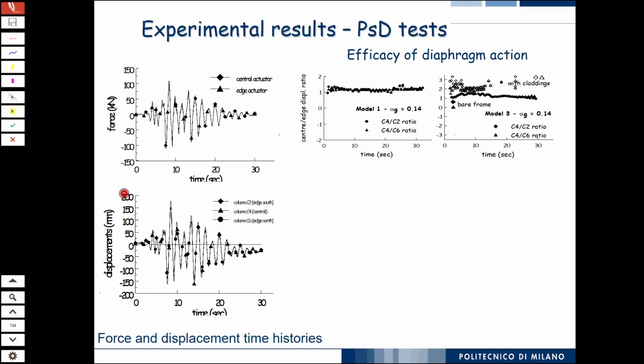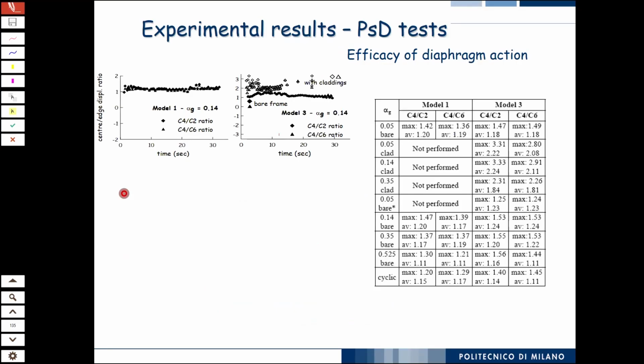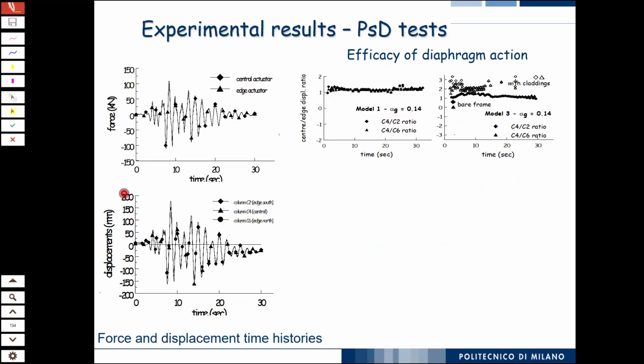And you see, what did we measure? Well, the first thing that you measure is the force that you are applying versus time. And these are the displacements that you record versus time. Okay, that's fine. But then, what we did, we went and we calculated, because we designed this structure to have perfect diaphragm action.